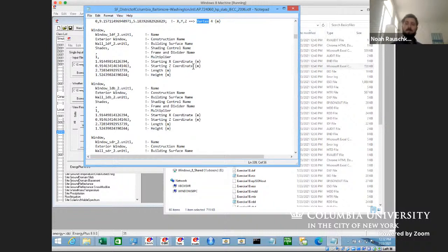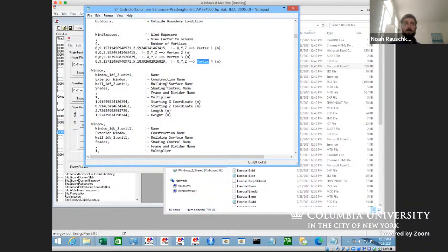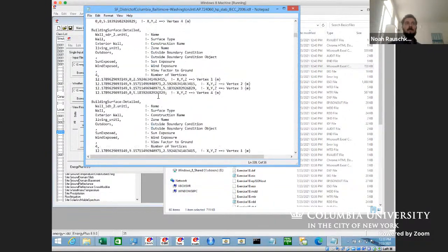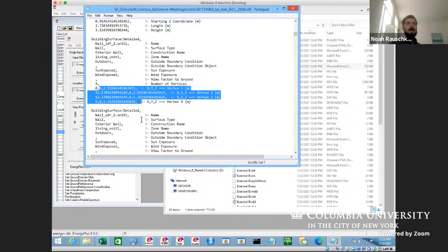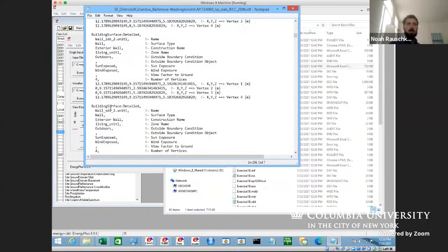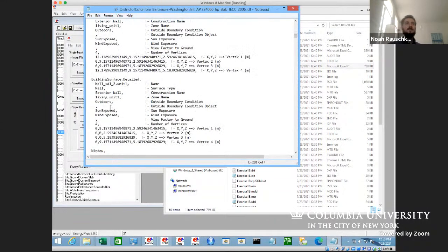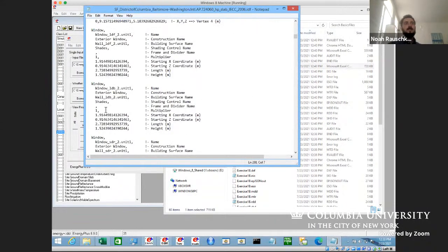Yeah, you don't need to define the geometry of the duct. No. But there can be a lot. So this building here, which is the prototype building, is much more complicated than anything we could imagine building manually. And you can look, we were struggling, all 5 of us, doing the vertices for a really simple wall where everything's whole numbers. So you can imagine if you had to manually define the vertices of your walls, and if you want to put windows in the walls, they all have to be coplanar, and all the surface normals have to be in the correct direction. So it gets really, really, really complicated.